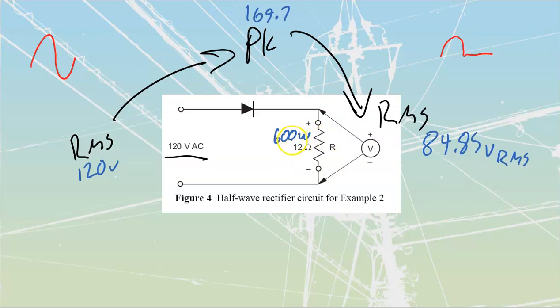What do we know about this voltage? Well, we know that on this side here, when we rectify this, at this point where we've got 0 volts over top of that resistance, we're going to have 0 amps of current. So 0 volts, 0 amps. Then when I get peak voltage, I'm going to get peak current, then I'm going to get 0 volts, and I'm going to get 0 amps as a result of that. And then over here, I'm going to have 0 volts, 0 amps, and over here, 0 volts, 0 amps, etc. So I can once again play connect the dots, and I see that I'm going to get a current waveform that's going to look like that, and then it's going to flat line along that axis.